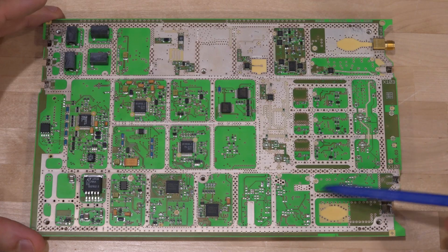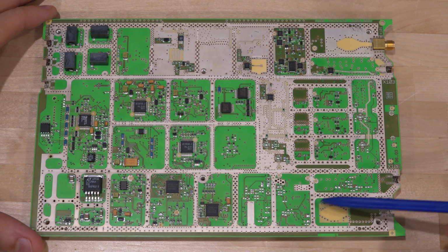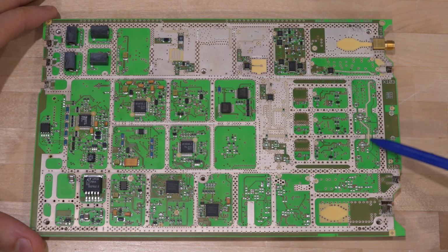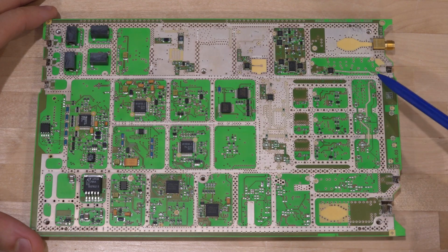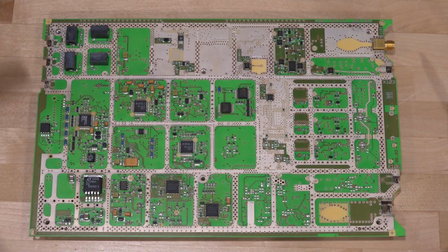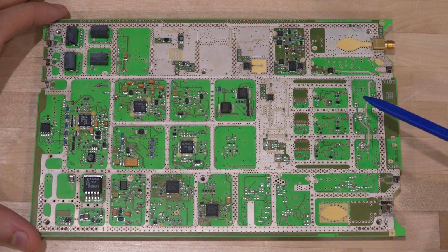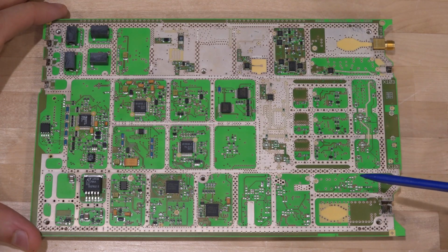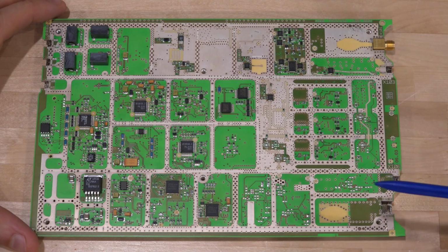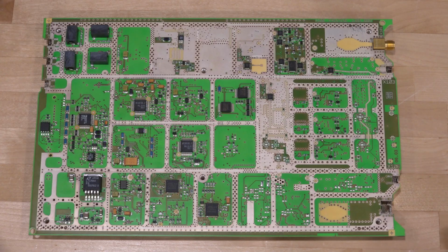We can see that there's an unpopulated portion here. My guess is that this is the tracking generator. I'm a little bit surprised that it's not populated, and there's a whole bunch of components here that are probably tied in with this that are not populated. Normally they populate everything anyway, and then you enable something with a software option, and otherwise it's not there. For a tracking generator, the connectors and everything add up to the cost and the components. That's probably why they haven't done that. So they run this in multiple versions, one with and one without it.